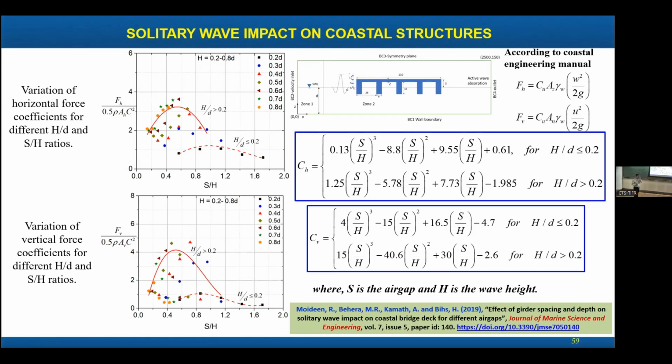Once you find out the force coefficients, you use that and multiply with this area or this expression. You have area here, horizontal projection area or vertical projection area. To find out vertical force, you use the horizontal projected area. To find out the horizontal force, you use the vertical projected area and find out the forces. That will be used for designs.